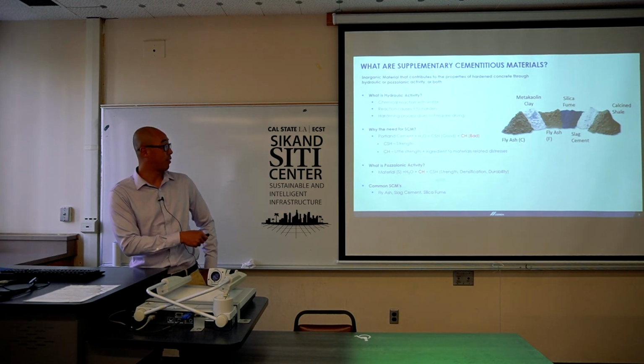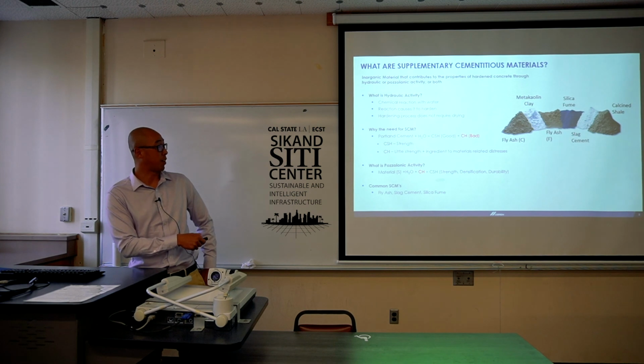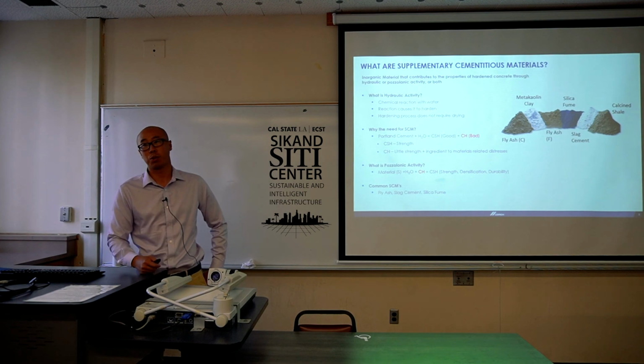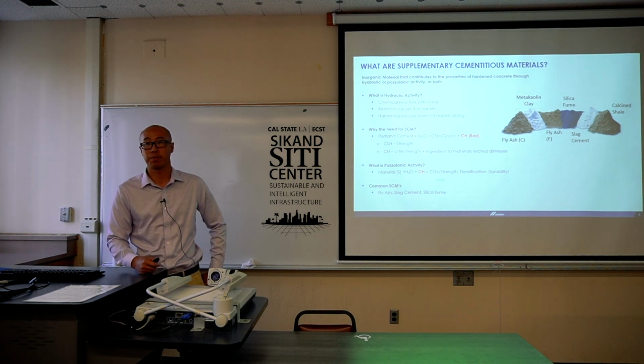This is the conventional concrete: the Portland cement reacts with water, and the supplementary cementitious materials react with water and the bad stuff, to reduce the CH and form more CSH. Both of those reactions need water. So no matter what, you need to keep the moisture in your concrete mix during the curing process.